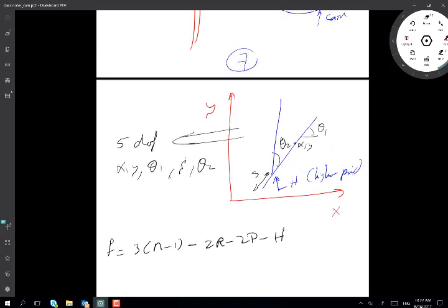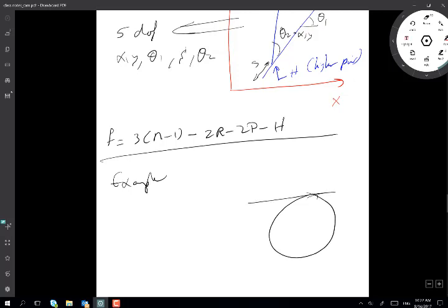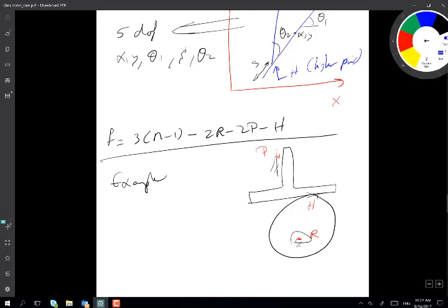So if I go back to my example there and try to solve it, now I have the cam and the follower here, and that's a higher pair. I have R, I have prismatic P. Right, let's count the number of links. Link 1 is all the frame, all the constant, fixed, stationary links, that's 1.